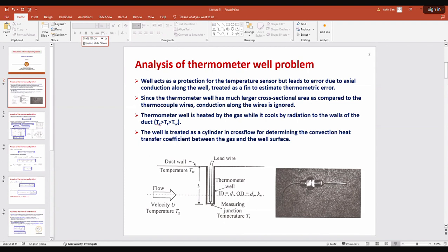Yeah. So what happens is, if you just put a thermocouple right on the tube surface, the thermal connection between the fluid and the tip is very weak. For example, here you did not create this cavity, you just mounted it here. The thermal connection between the tip and the fluid is very weak because the heat exchange area between the tip and the fluid is very little.